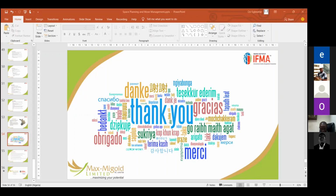Normally, if you are going that high, sometimes you see some buildings, you have a little bit of jut out at the end. We call it overhang, where you can put your condensers for the air conditioning system. People don't know why you design those things. It's because you can place the air conditioning system and you put a point where you can have access to go and service. But for an architect that understands facility and understands maintenance, it's easier for him to make those provisions.